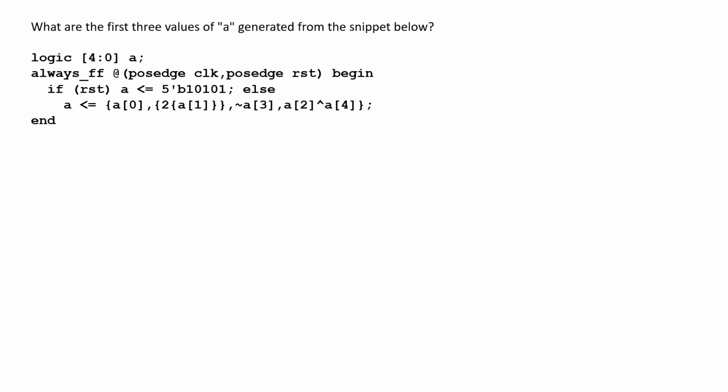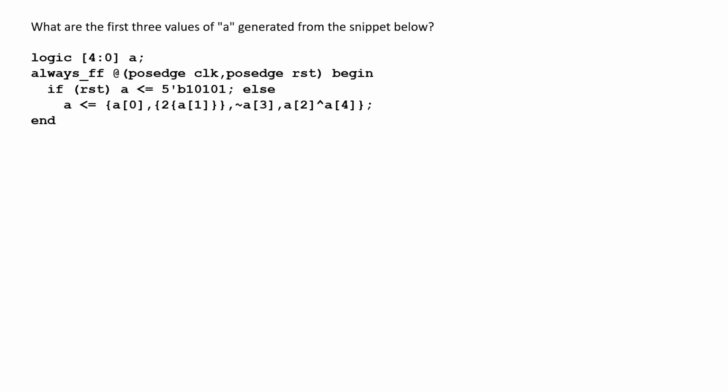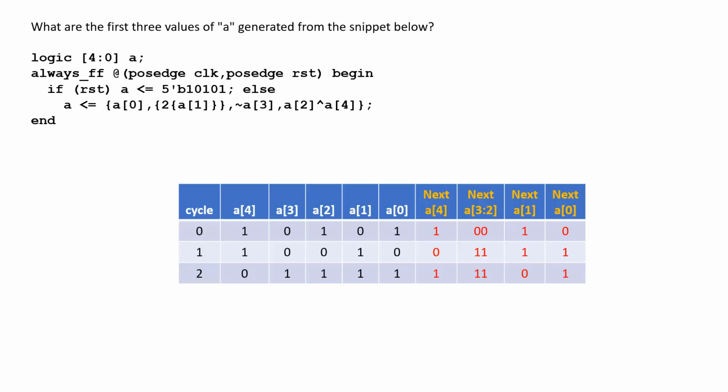So that's 1 plus 2 is 3, plus 1 is 4, plus 1 is 5. So luckily, when you add up all the bits that you're concatenating, it works out to be 5 bits. What if there was an extra? Would it just truncate the end? I think it would truncate the beginning, the most significant bit, is my guess. But it would give a warning. Yeah. But you might miss that warning because there's a lot of warnings that you get when you synthesize.